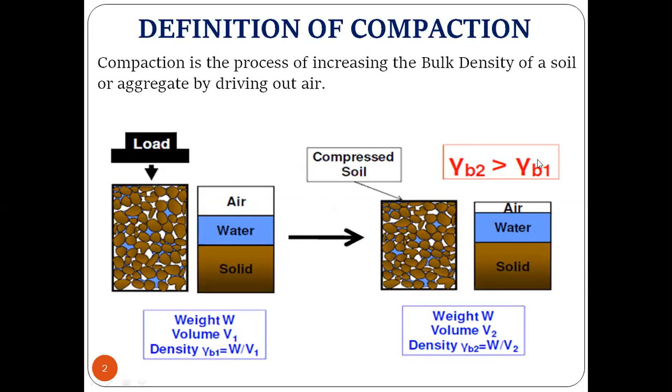So this is the process where we apply the load, due to which the air present in the soil voids will expel out. For this process we spray some water so that the soil particles become softer, and so that we can get a good, denser soil.